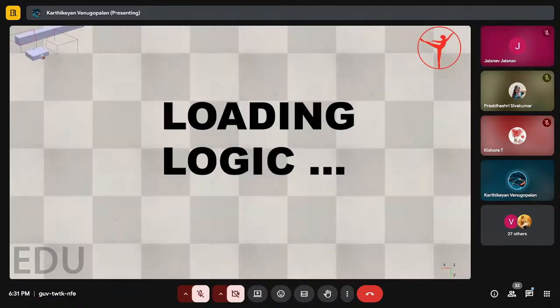Yeah, exactly. So what we are going to do here is have one proximity sensor in the front and detect the front obstacle. If an obstacle is detected, we are going to tilt the bot by some degree until the object isn't detected. Obstacle avoidance is a basic thing for every kind of bot you move. For any bot, environment detection is important, and for that you need a proximity sensor, and the concept behind it is obstacle avoidance.